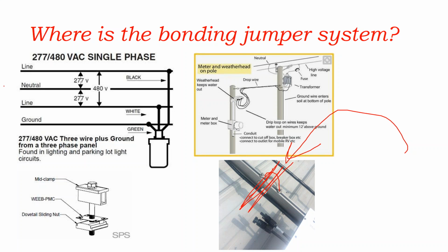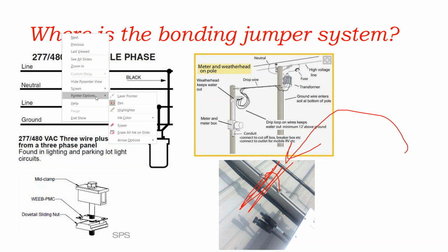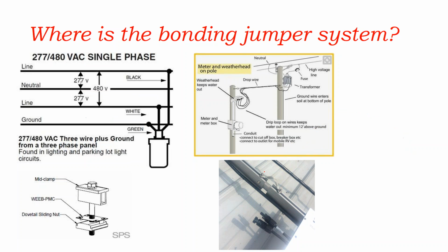So what you have in the solar industry here is what's called a bonding jumper, that even though we have two sticks of metal rail and a splice, and it's a metal splice, it may not be listed as a bond path. And so we have an additional bonding jumper that is our listed path. You might have a metal pile going into the ground. It may not be listed as a ground path.